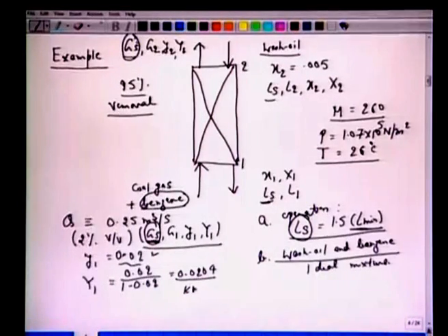This is nothing but kilomole of benzene per kilomole of dry gas. Notice this nomenclature, the terminology dry gas. That doesn't mean that it has moisture. All it means is that it's a benzene-free gas. So that's the meaning of dry here.